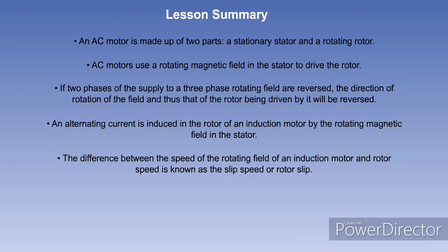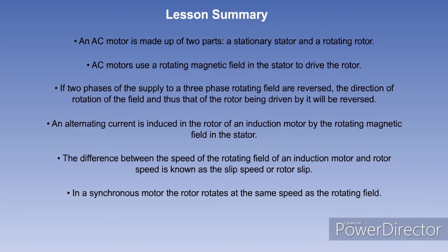The difference between the speed of the rotating field of an induction motor and the speed of the rotor is known as the slip speed, or rotor slip. In a synchronous motor, the rotor rotates at the same speed as the rotating field. Here is the formula for calculating the speed of rotation of a synchronous motor.